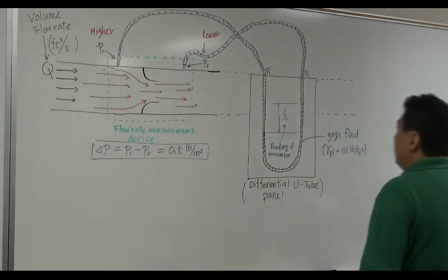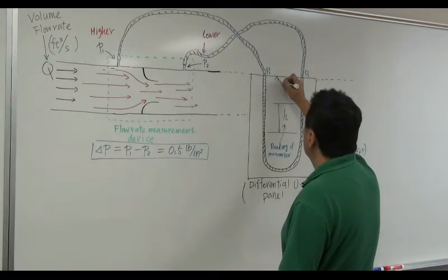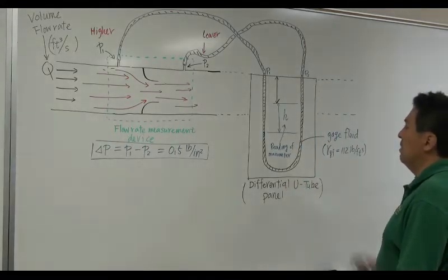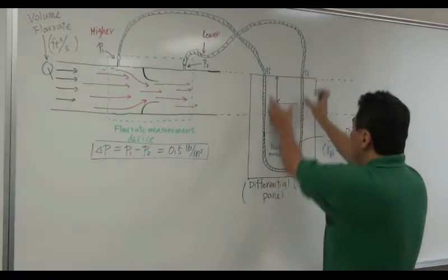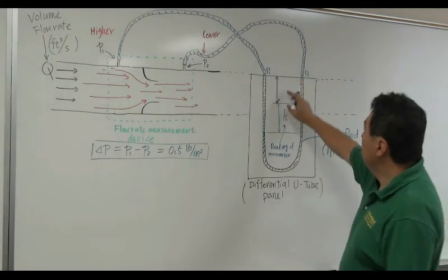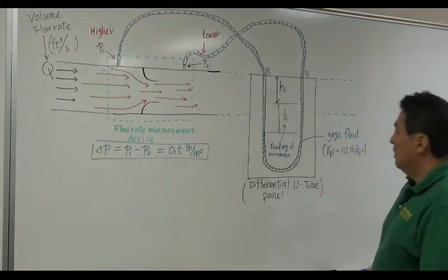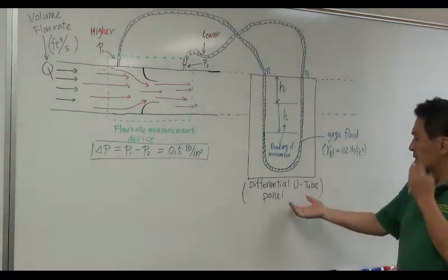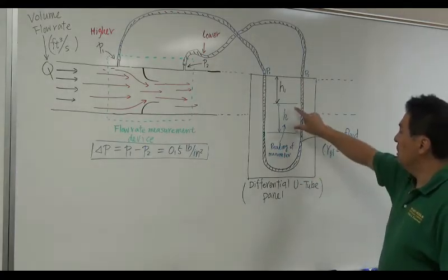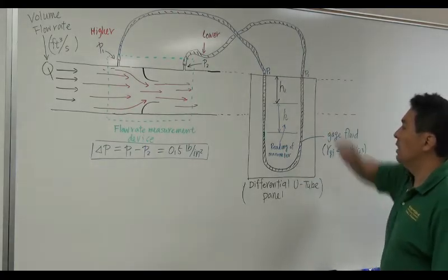Well, first of all, this is something we really don't know. You can use a very long U-tube or a very short U-tube, either way is fine. So this is a variable. Let's call this H1. Can we use any differential U-tube manometer? Yeah, sure, of course. The only thing that matters is this H, not H1. But H1 is unknown, so let me just put H1 here.